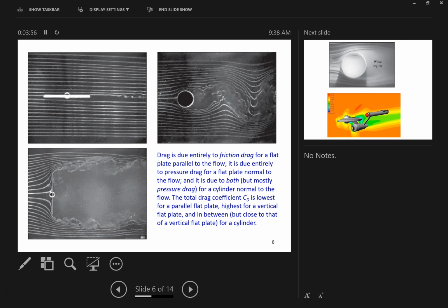Where this one right here is spun around, now you have this big frontal area where the wind is blowing, hitting it. This is what they call pressure drag. Okay? If you notice, you still get a little bit of pressure drag in here, and you still get a little bit of surface drag here. But 95% of this is pressure, and 95% of this is surface drag. However, looking at a sphere, that's almost 50-50. It has both pressure and surface drag. And that's kind of how they classify types of drag: pressure, surface, and the sphere.